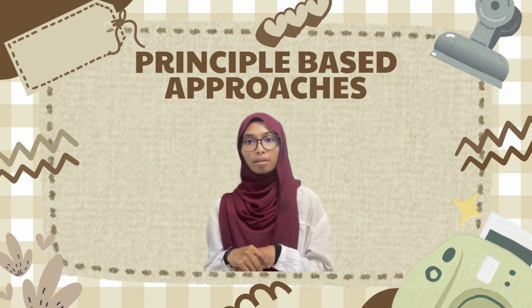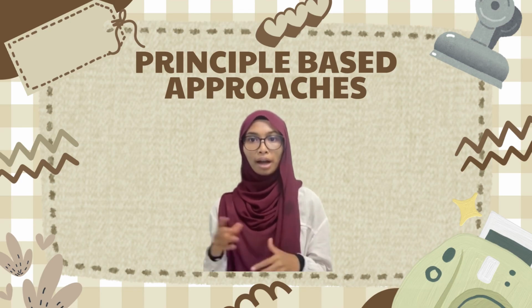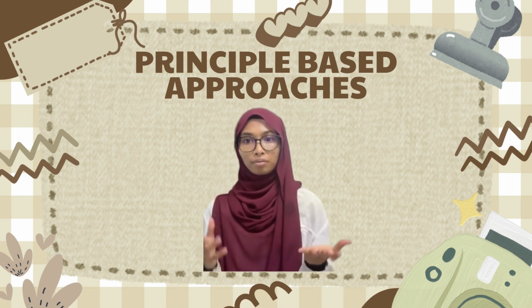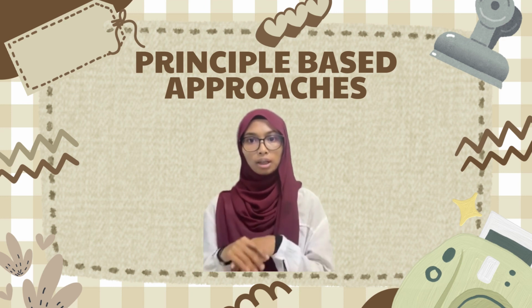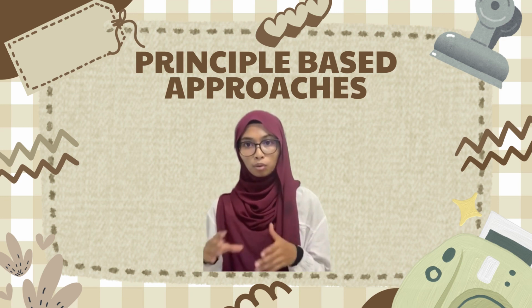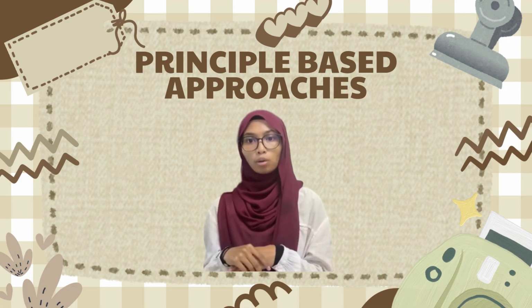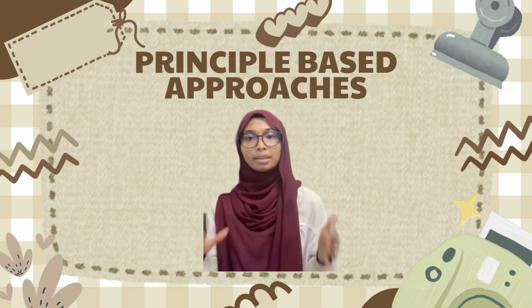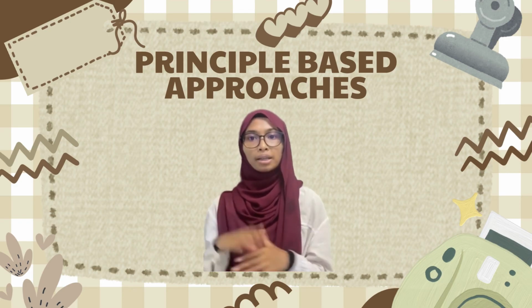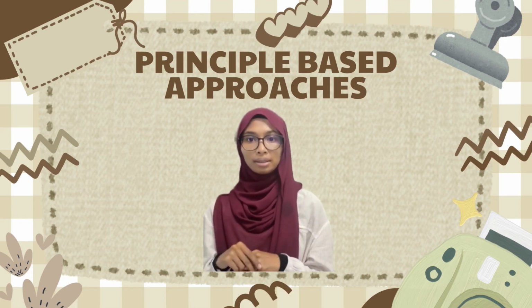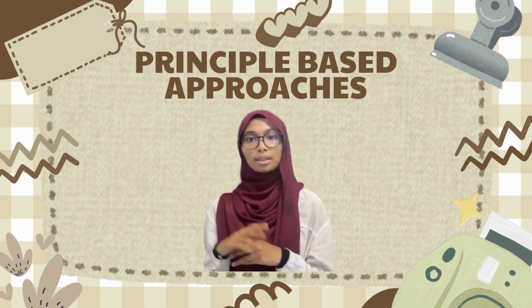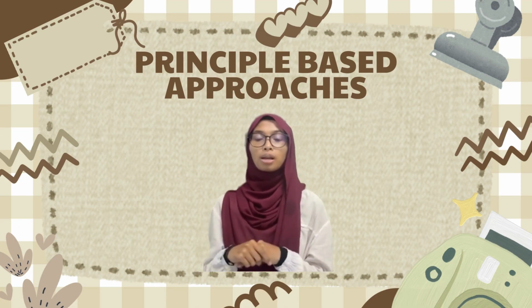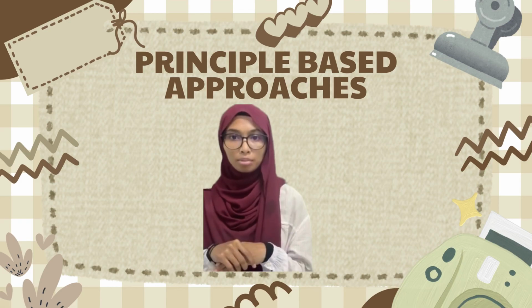With only a capacitor and resistor added, the ideal integrator amplifies DC voltage infinitely. Every op-amp has a small, unwanted DC offset. This offset was continuously magnified until the circuit failed. By adding a 10 megaohm bypass resistor, we fix this DC drift and make the circuit stable.